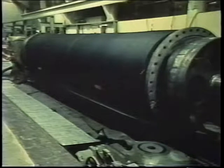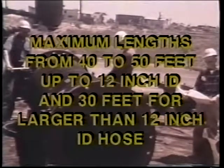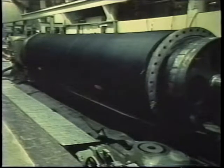Larger diameter hoses with or without a helical wire are also hand-built. This method of construction also permits the use of a wide variety of tube and cover compounds. Diameters of hand-built hose can be as much as 36-inch ID, having a capacity to move very large volumes of material. Maximum lengths are from 40 to 50 feet up to 12-inch ID and 30 feet for larger than 12-inch ID hose. Due to the high degree of hand labor involved in this construction, these hoses are relatively expensive.